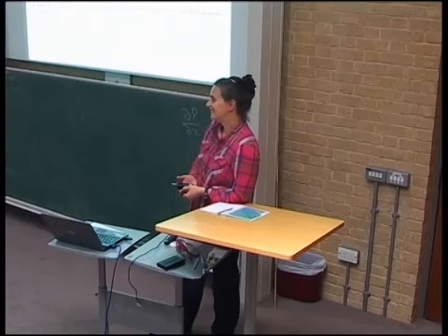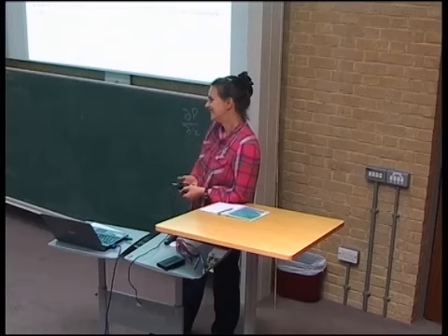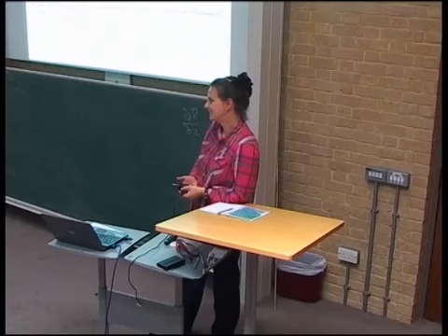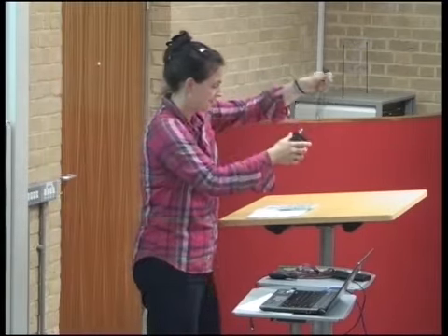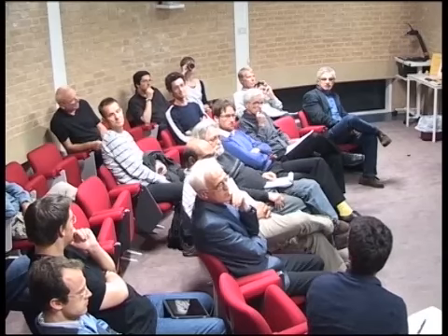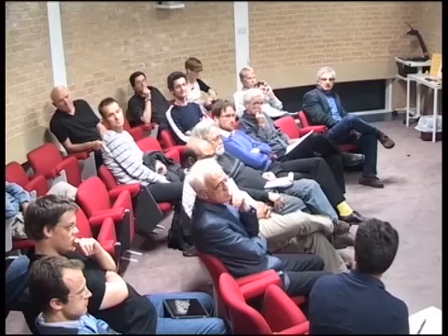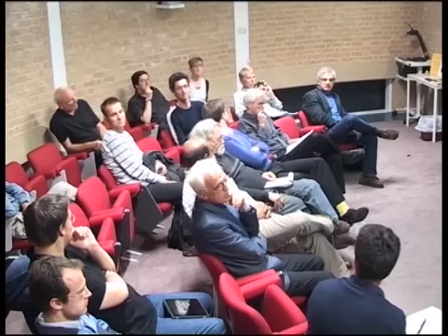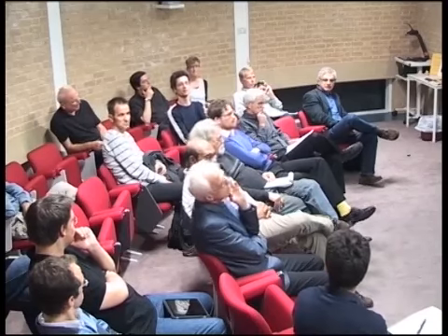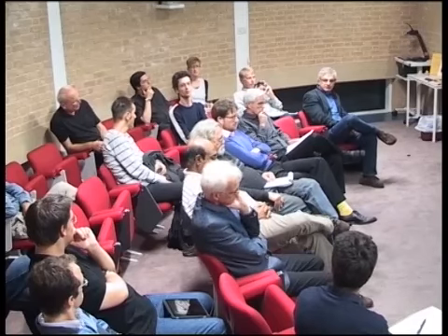No, I'm coming from a different angle, but people who have looked a lot at this and at the consistency of the mass and momentum equations, people with compressible flow in aerodynamics, solve implicitly. Yes, with a Newton solver. Yeah, but that's for high Mach number, right? For low Mach number, there's a completely different story. We've never been able to beat an IMEX method with a fully implicit method, not for low Mach number flow. I agree with you for the high Mach flow. Yes. But you also get non-linearity is not